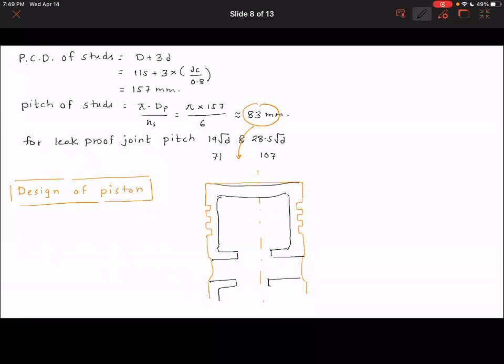And usually the simple pistons can be machined. For example, if you look at the weed whacker pistons or pistons for a very small engine, they can be machined on CNCs. But many a times the large pistons are typically cast and then machined. So you have additional ribs to strengthen the piston.